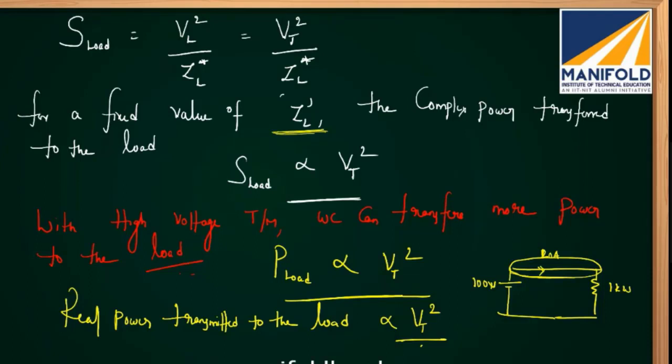But at very high voltage transmission, which we'll discuss in Corona, we increase the size of the conductor intentionally, not by wasting the conductor material. We use some other techniques there that you'll learn most probably in the next class, where by increasing the overall size of the conductor, by using some filler material or by interconnecting other conductors, we reduce the electric field intensity surrounding the conductor.